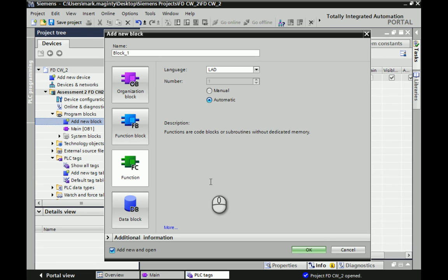For the car park, from memory, I think it is 4 outputs, which are going to be 2 for the barriers, and then a further 2 for the lights, which are full light and spaces light. And then the inputs, I think that all 8 are used from the car park. So you have I0.0 through to I0.7 being utilised for inputs, and then 6 for the traffic lights outputs, and a further 4, so it's 10 in total if you're doing the complex version of I/O that you will physically connect to.